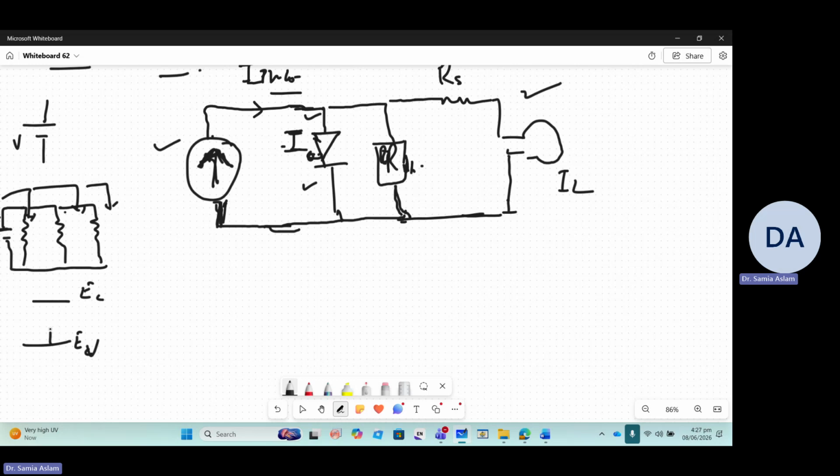When the electron gets excited, after some time it will de-excite naturally and go back. We don't want this process. We want this electron to forever separate from this pole and go into the external circuit. If this electron cannot get separated, before it goes away it gets recombined. So basically this is the resistance in the path of the electron extraction to the external circuit, and this resistance is known as R shunt.